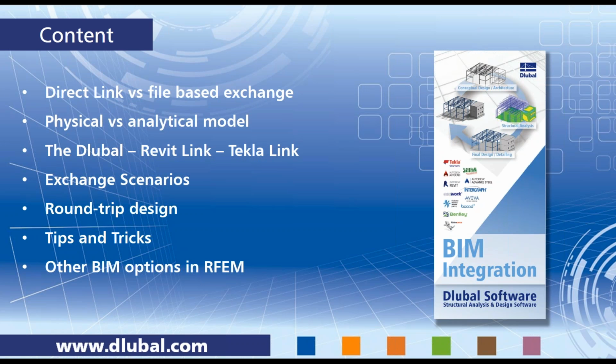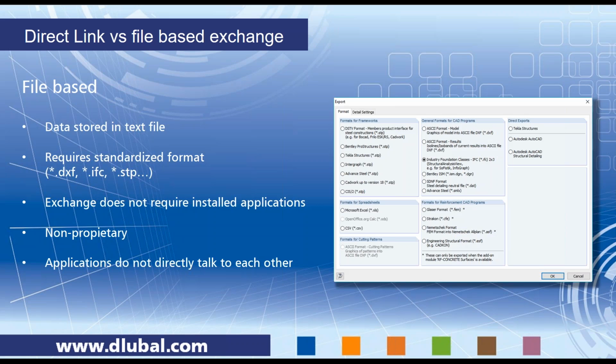The file-based exchange, as well as the direct interfaces, all come with RFEM automatically. When we use a file-based exchange, however, we have to translate more or less the data that we have in RFEM or in the CAD software into a standardized format. Depending on the specification, what entities and what kind of objects these formats provide, we may or may not be able to write our data into these files.